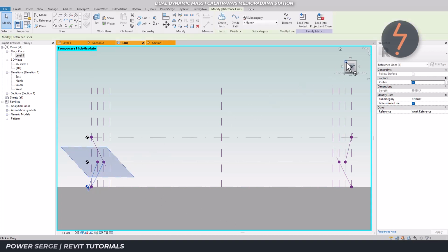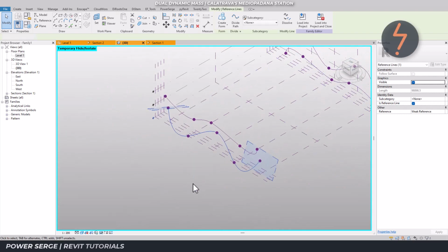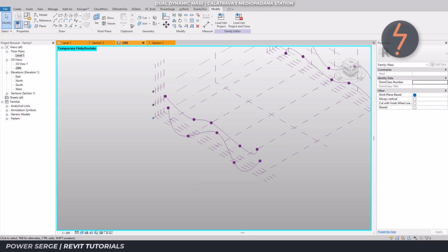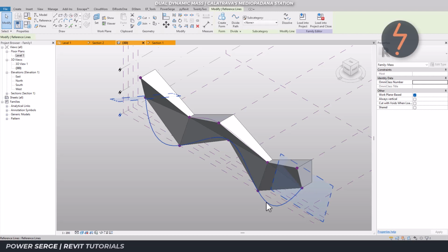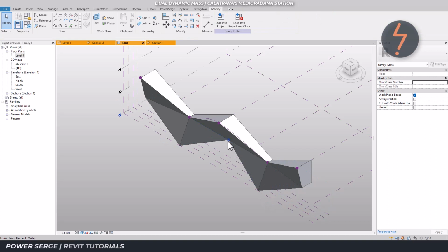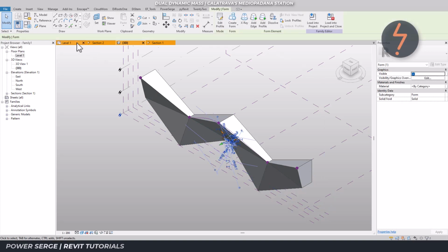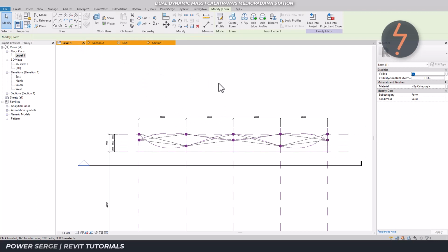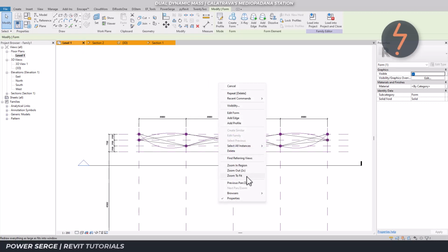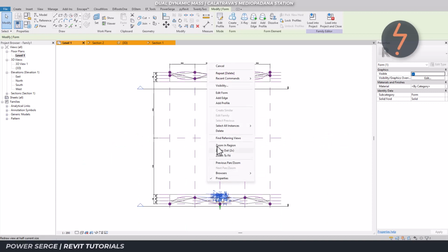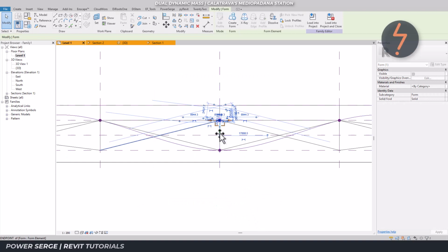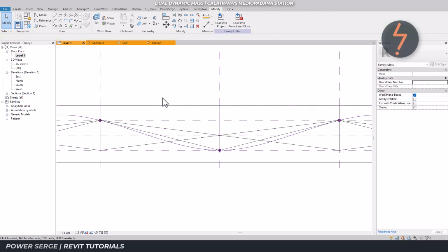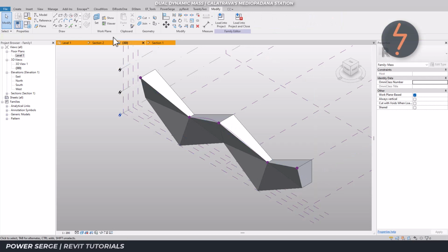It serves to show the importance of zooming in sufficiently to ensure accuracy. So I'll pick it up from a zoomed in view. I can select the defunct spline and delete it. This will also delete the hosting points. And I need to project this point to reference line 3. It's currently on reference line 2. Then I can recreate the spline.